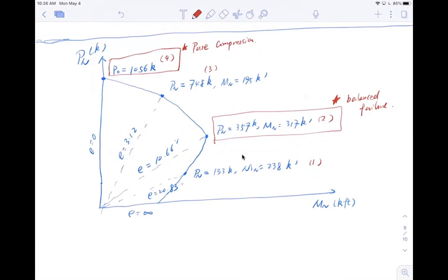Once you have these two points locked, all you need to do is pick a point here, and usually we can set this to be 0.0075. At this point we set the compressive zone C for the concrete. C bigger or equal than D, which is depth. All you need to do is draw these 4 points. Once you have these 4 points, you can finish the interaction diagram.